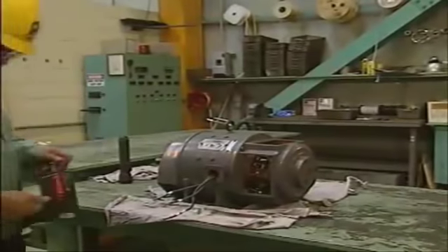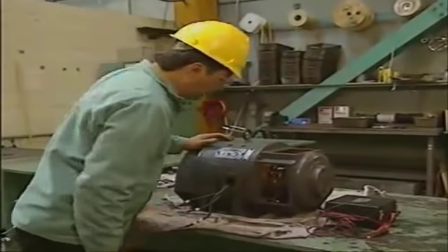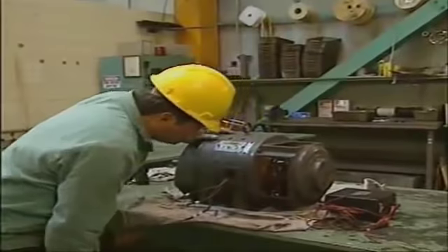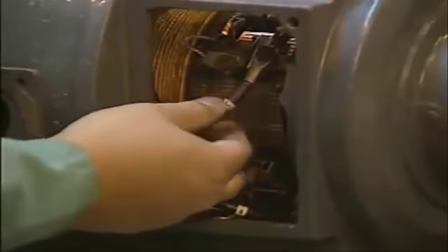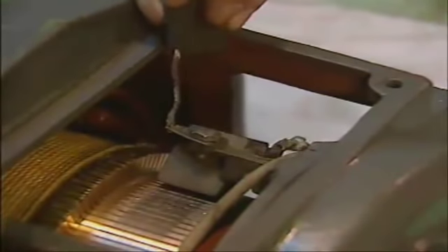The motor in this example has been taken to a shop for troubleshooting. First, it should be checked carefully for any obvious problems, such as broken wires, loose screws, short brushes, and charred insulation. The brushes and the brush rigging should also be checked. The armature and field windings are also checked. It's common practice to look for grounds, opens, and shorts. These are the problems that occur frequently in all types of electric motors and can prevent them from operating.